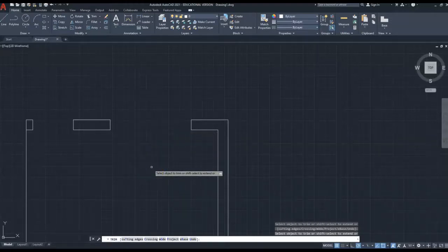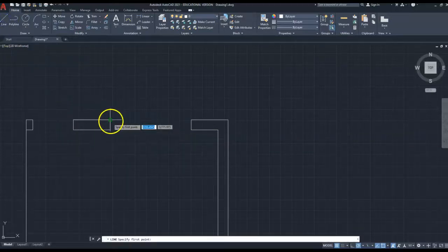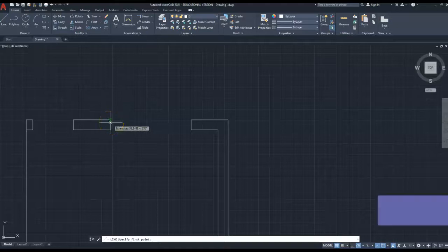Now, door openings normally stay open like that. Window openings are normally designated by a couple of thinner lines, just slightly inset. So what I would do, I'm going to click escape, and all I'm going to do is select the line function, and I'm just going to come in 30 mil or so. Doesn't matter. It doesn't need to be dimension critical for this point of view.